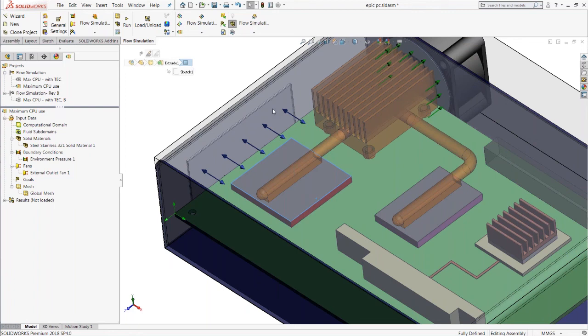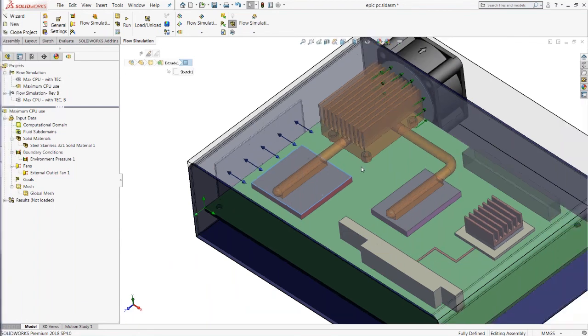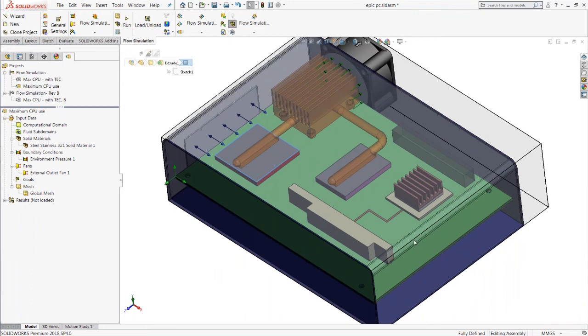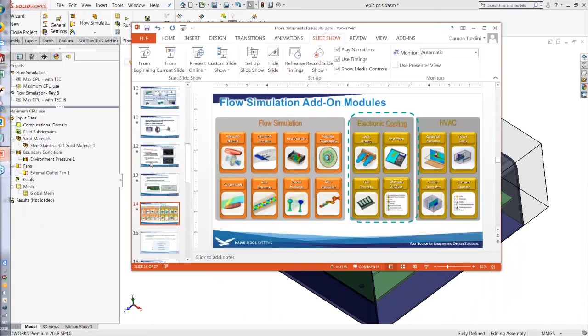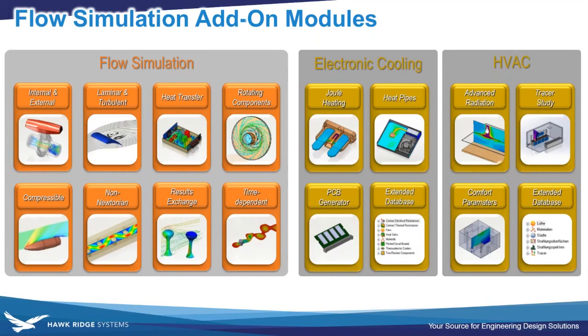If we were to just put a solid material on that chip, the way I just did for the case, I'm going to be pretending that the thermal resistance or thermal conductivity throughout the chip is just the same in all directions. And we can tell right away that that's not, again, a very good assumption, right? We know that the heat is going to get out of that chip to the bottom of it, where the board goes, differently than to the top where this heat pipe is connected. So how do we account for that, or other factors like what the inside of this PCB looks like? Well, that's where these capabilities in the electronics cooling module will come in.